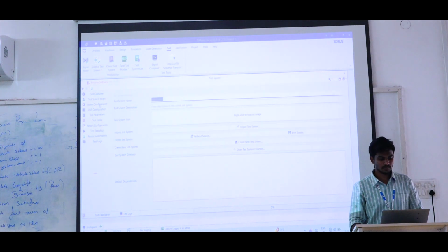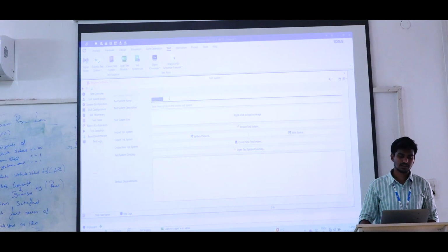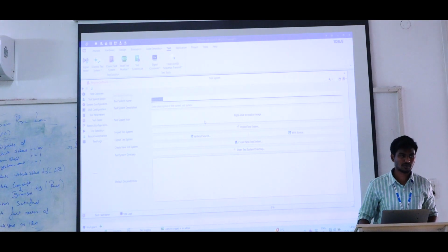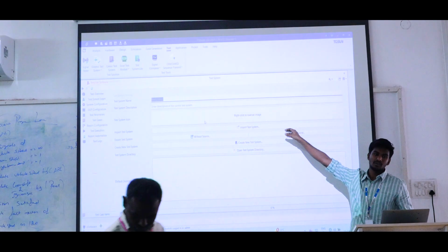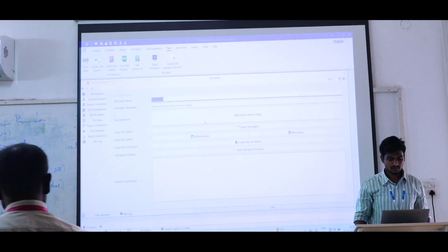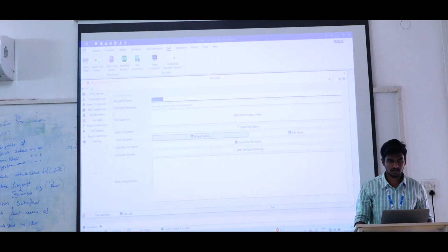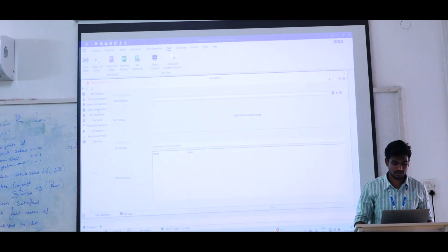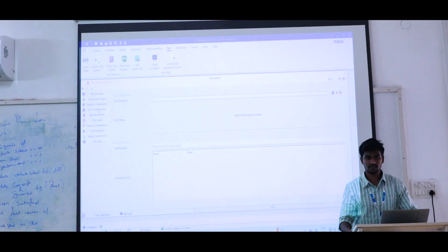So the third one is system configuration. It is for what kind of test system we are writing, the basic configuration only. Whatever we select, the system icon is for the test case we are providing. It means you are working with the engine test case, using the engine image. If you have previously worked with any test system, you have to import it here, and export means we have to export it here. Now the fourth one is the DUT configuration. The DUT is nothing but device under test. That is our ECU.